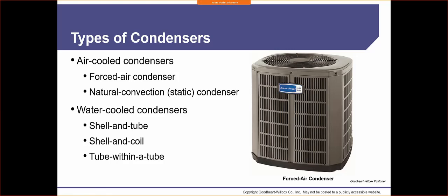Sometimes people put these under decks, all right? Well, I'm not getting a good heat transfer rate because I've got a deck over the top of it, okay? The other thing too is because we've got this air sucking motion coming in through the sides, we get things that get stuck inside the coils, all right? The coils are just these little fins. Sometimes they're called spine fin coils, especially on American Standard Trane.